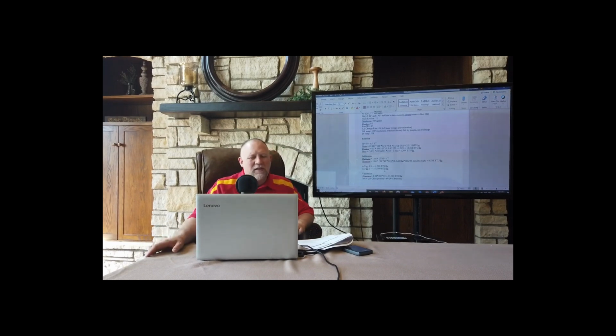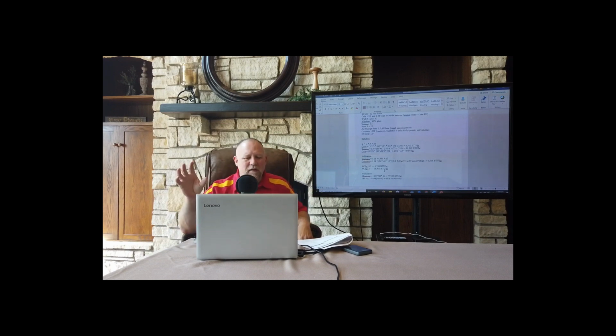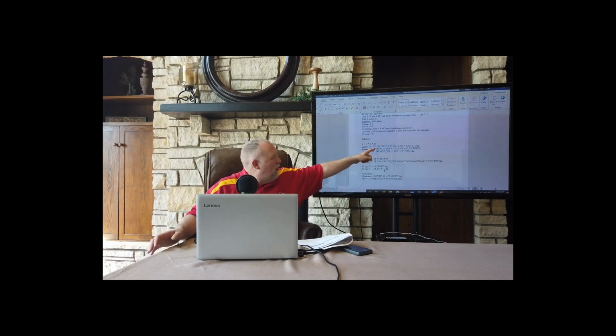The way that you approach this, and notice I wrote each of these out. I want you to do that for your homework and for the final project so we can follow it along and check your work. Equation: UA delta T. The U value for a wall is the inverse of the R, so that's where we get 1 over 12. Next, 60 by 12. The total length of those walls is we have a 40-foot wall and a 60-foot wall. At the worst time, it's at night, and it's got the same temperature across both walls. So let's just call it a 60-foot wall that is 12 foot high.